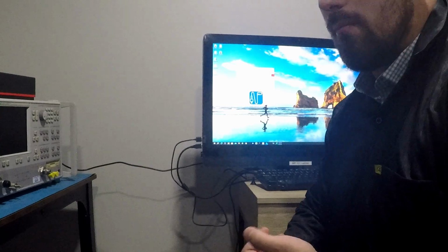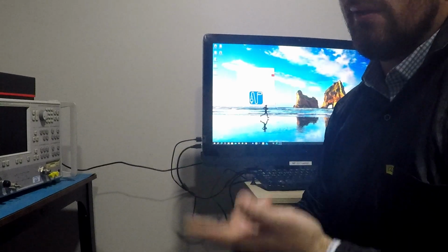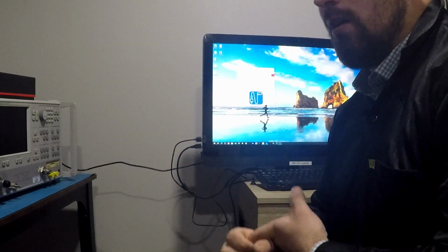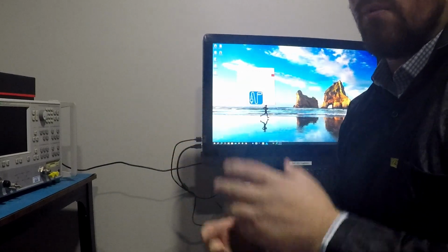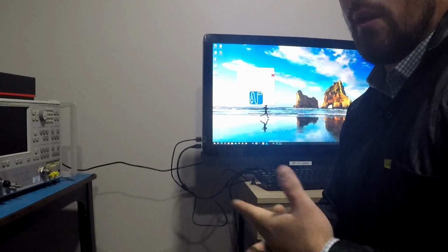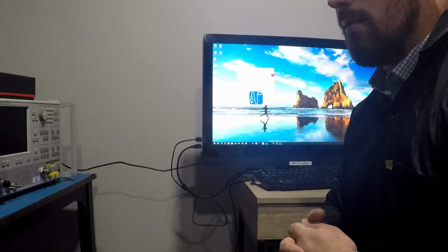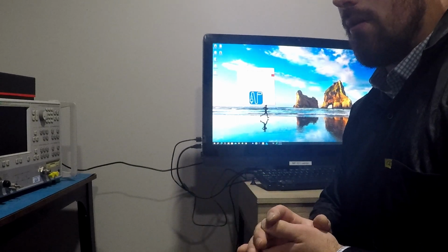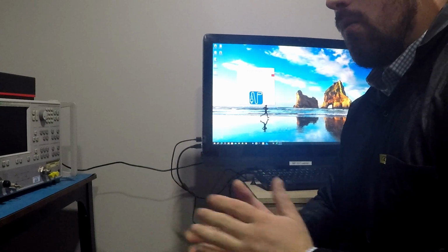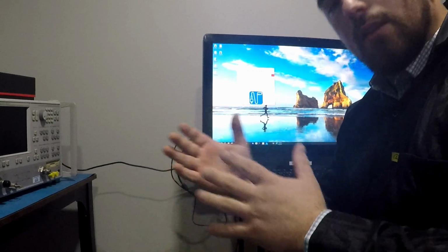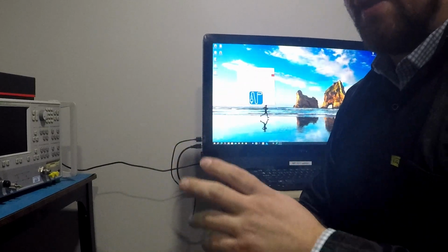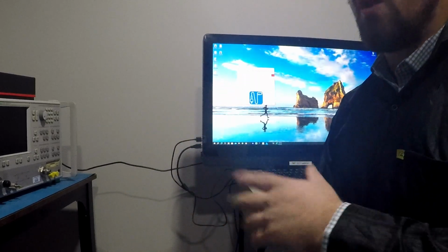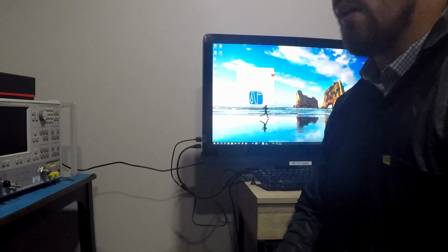We'll see. I'll probably do multi-band. Since we know it doesn't work below 4 gigahertz, I'll probably just do like 5, 6.4, and 7.8, 1.4 gigahertz bandwidth spacing. So we'll have it solved for that, and then for individuals, so we'll have it be multi-band, those 3 bands, and then we'll also do a broadband for 5 to 8 gigahertz. Let's just go with that since we're already solving that criteria.